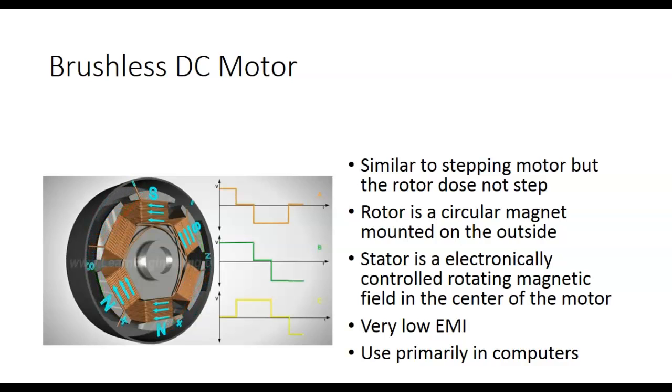A servo motor is a motor that provides feedback. So not only do you run it at a speed, it tells you how fast it's running. Servo means feedback. So we call it a closed loop system. We call it a servo system.